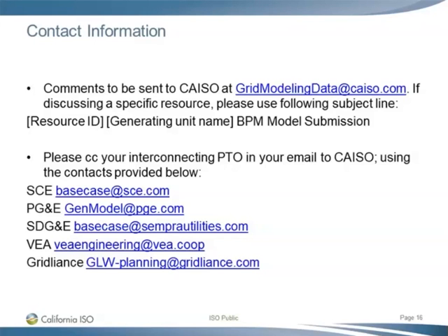Yes, so type 1 and type 2 wind turbines, they are not required to provide EMT models. Okay, so they're not required to do that. Okay. Yeah, they're exempt. Okay, and I'm assuming the inverter-based systems don't have to do this either, right? Because I noticed you are only focusing on synchronous and induction generators. No, all the inverter-based generators interconnecting at 60 kV and above, with size greater than 10 MW, must provide an EMT model.